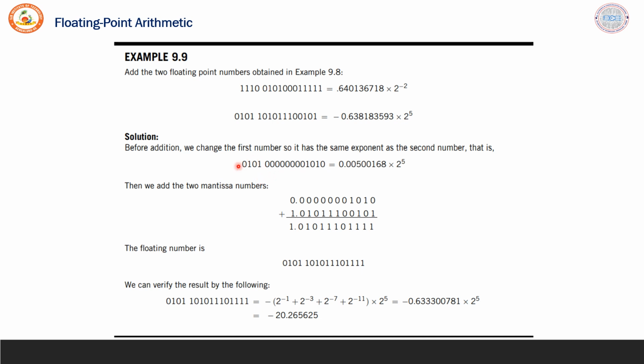The initial part is the exponent and the later part is the mantissa. So we take the mantissa alone and we add the mantissas. The addition results in an answer which looks something like this, and the equivalent of that can be found like this. Since the exponent is common, straight away we write the exponent to be equal to that of the greater value.